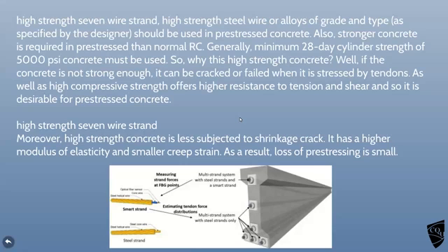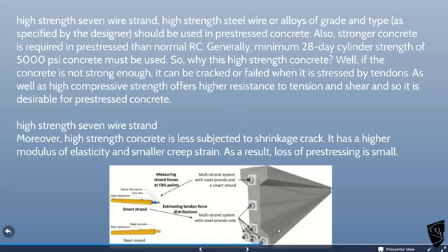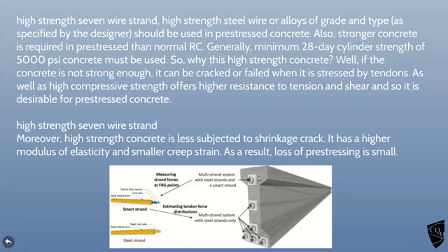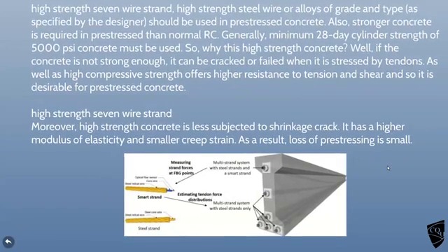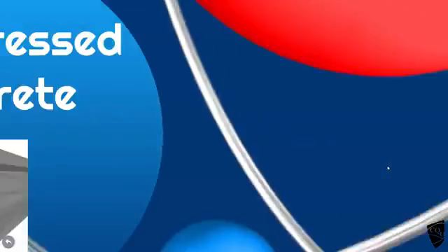Okay? Once this has got to its 28 days or whatever the design life was, you thread the bars through, you have a spreading plate on the end here, and then you use a pneumatic puller to pull them under tension, so they actually come out to a degree, and then it's normally a bolt, but you can weld them, and then you basically secure the end of it while it's under tension, and as soon as you take it off, it tries to shrink back to its original length, and it can't, so it starts to pull the beam together, it compresses it. It's really quite a clever idea when you think about it.